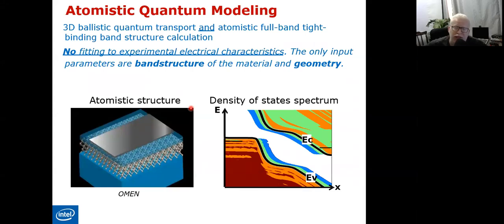Whenever you use devices scaled down to the nanometer range, the drift diffusion model can no longer be used. That's why this type of structure, either the TFTs, the tunneling field effect transistor, the thin film transistor, the organic transistors, all this cannot be demonstrated using the drift diffusion model. Accordingly, we need what's called atomistic structure modeling or quantum modeling in order to demonstrate such sophisticated structures.